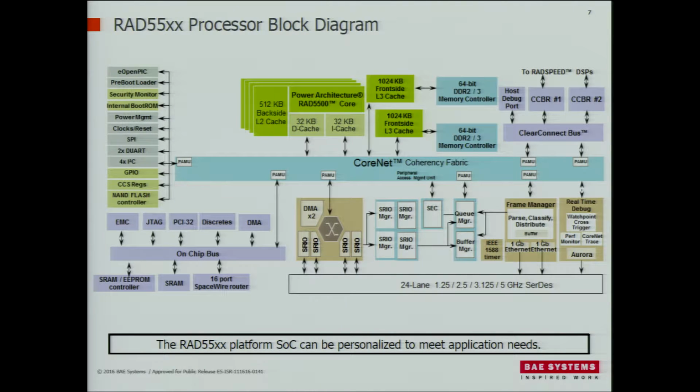I wouldn't expect that to ever be used on orbit, but in a lab integration environment, if you can stream out big chunks of data about what's going on in the system, that's a really helpful debug tool. That's in addition to the legacy heritage JTAG COP interface, if you're familiar with that. And then sitting in between those blocks is the DPAA function in the system.